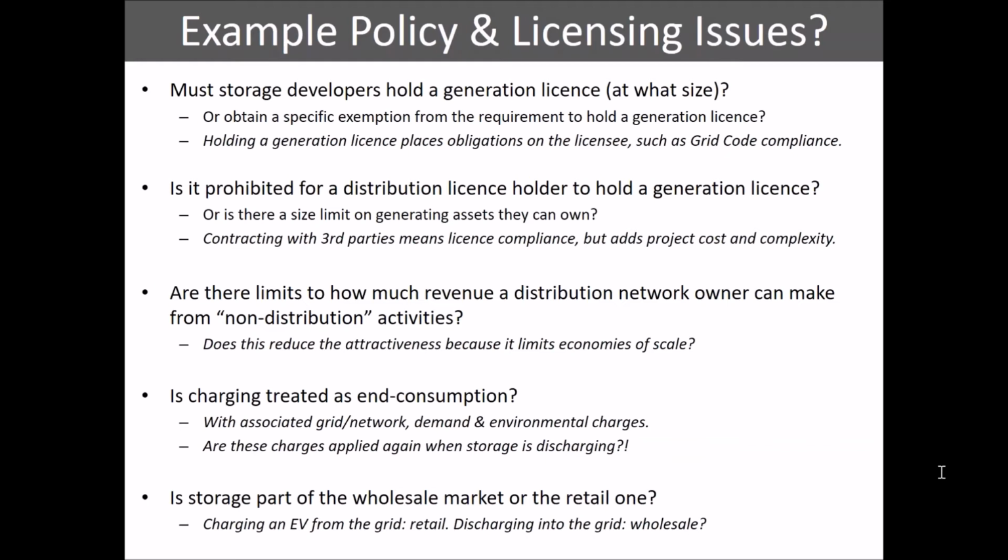In the UK, for example, there are problems if you're a distribution network operator in terms of being able to have generation in your system. There are limits on how much money they're allowed to make from non-core activities. So there are various things around that. Now, obviously, we've said that storage has some particular advantages if I'm a distribution network operator. On the one hand, I could save quite a lot of money in terms of upgrading my network if I could have some batteries, for example, at substations within my network, but I might be prohibited from owning those batteries because I'm not allowed to be a generator, and there are times when that storage is generating. That's one example. Again, there are rules in countries about transmission operators and what they can do as well.